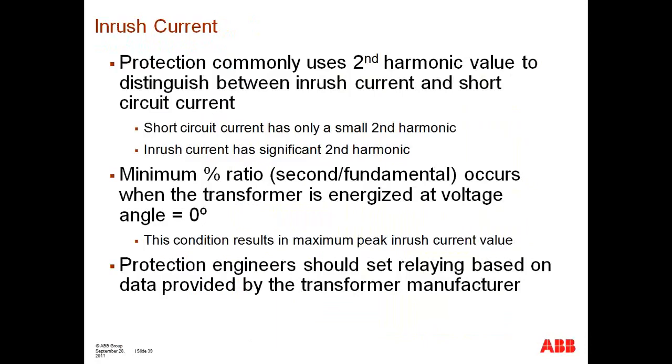Okay? And these are some of the fundamentals, though. The bottom line is that, from a best practice perspective, second harmonic inrush settings, used to identify that inrush occurs, really vary from 8% to 15%, and it's pretty important to consult the manufacturer of the transformer, since for the most part it's a function of some random components, such as the point on wave at which the voltage closes and so on, but it's also a function of the manufacturing characteristics of the transformer. Okay, so again, anywhere between 8 and 15% is reasonable.